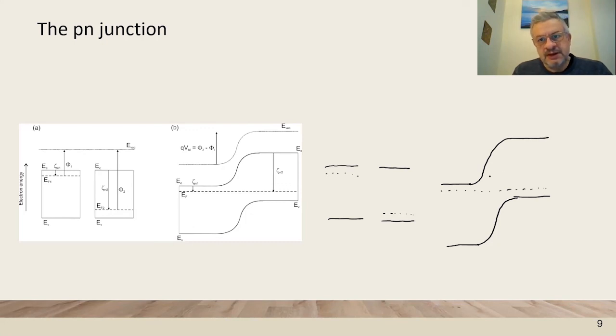And this is different from the contact potential difference because this region is quite extended. It will depend on the doping. When there is less doping, it will be more extended. So this is like two Schottky barriers back to back. And when we bias the semiconductor PN junction, then this is going to come here.